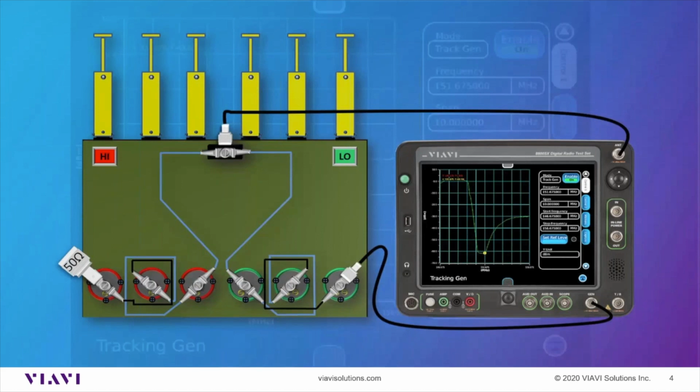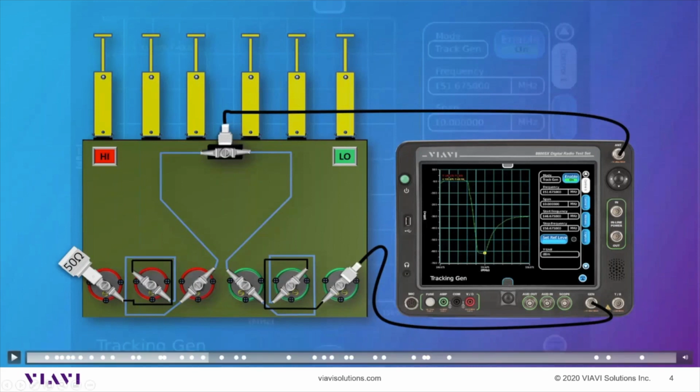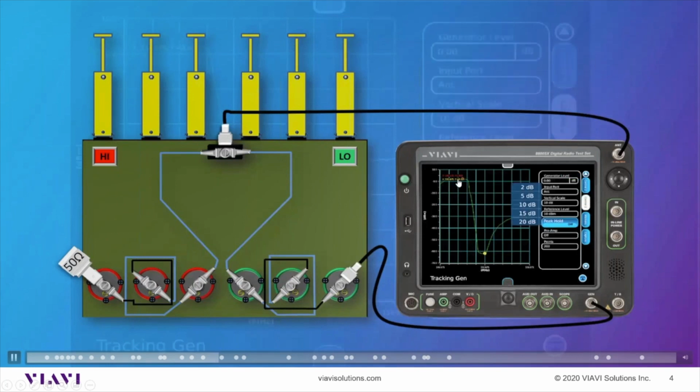So if you haven't tuned a duplexer before, definitely get some experience tuning these, because you're going to see a little bit later when I put the return loss bridge on there, there are some really fine movements that you have to make, and you've got to get used to doing that, or it'll make your day very long. So we're just going to continue on, using our plungers to clean up that frequency response on the low pass that we're on right now.